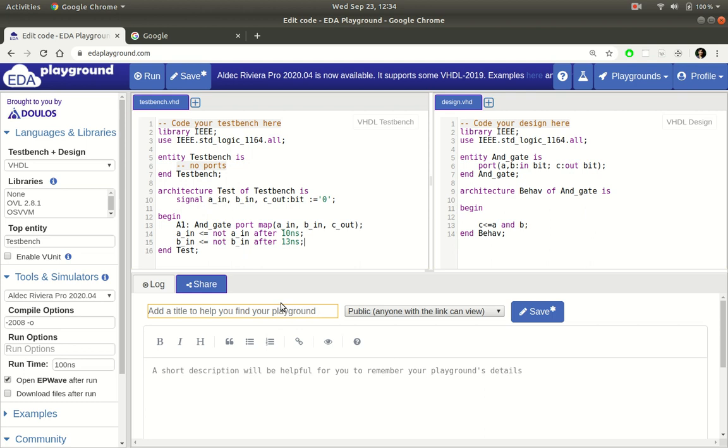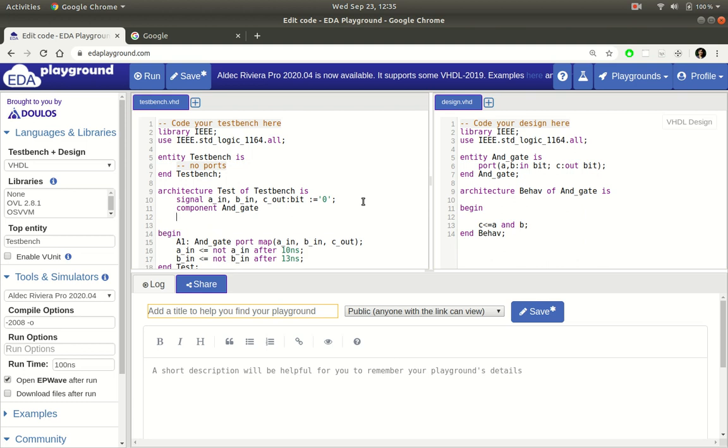That's it. Now one thing is, notice that I am using this AND gate, so I have to tell the test bench entity that this AND gate actually corresponds to this definition, and that it has these ports. So the way to do it is to declare the component. So I have to have a component declaration block. So component AND gate. Okay. I just have this line copied.